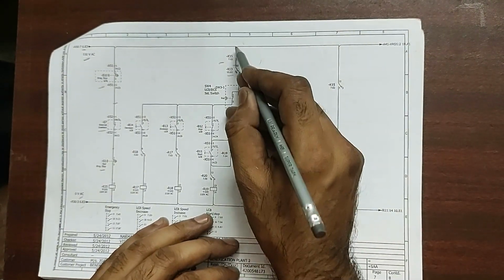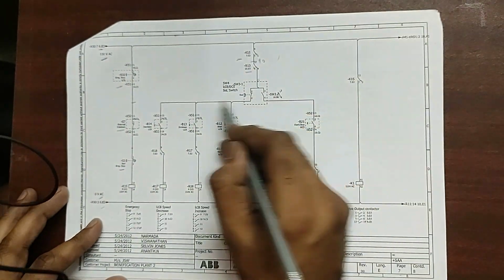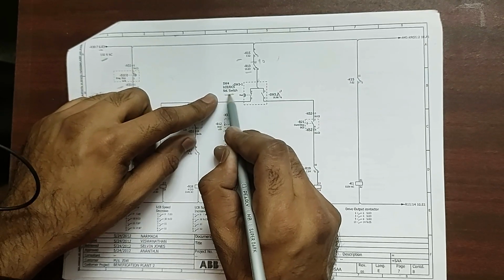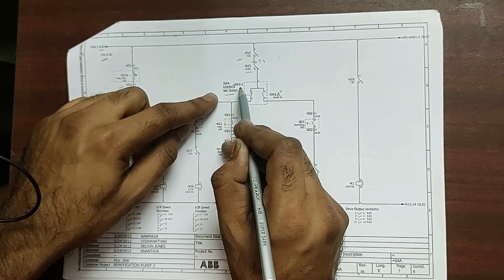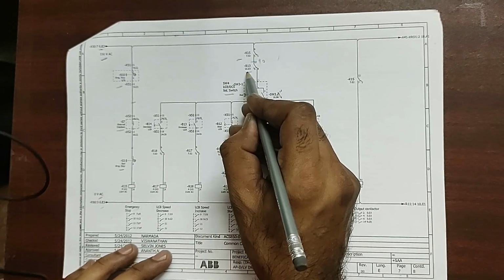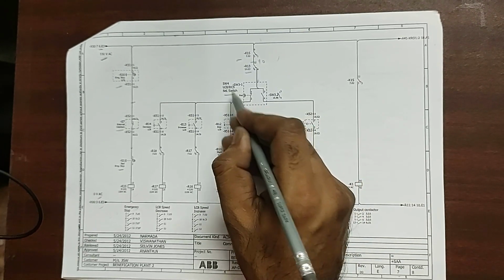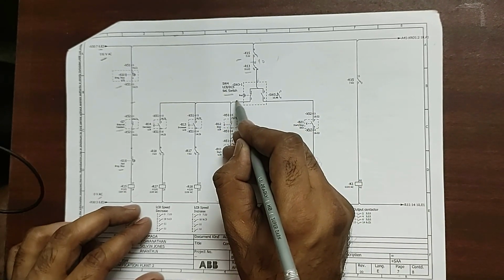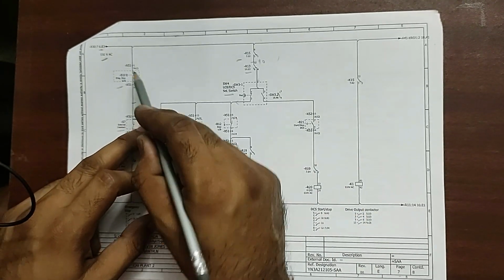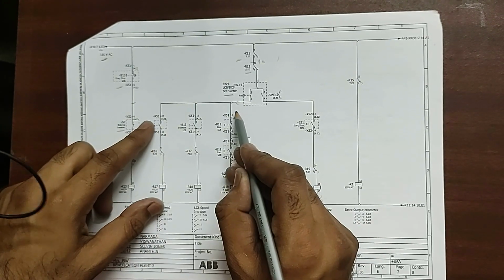So if it won't pick, then 110 volt will come till this point, and later on it gets distributed in two parts. This part is selected by this LCB DCS switch we have seen on the first page. So first select this part, the left part. Suppose we have selected the left part, LCB part. So supply will come till this point. This is X51, as we have seen X51 is LCB, and all these points have 110 volt.